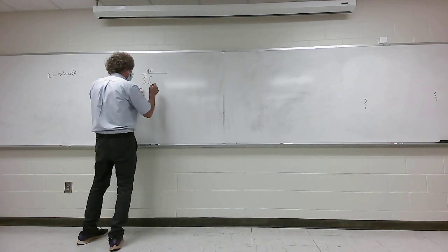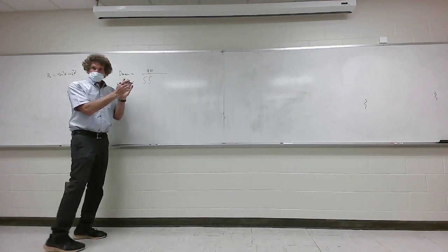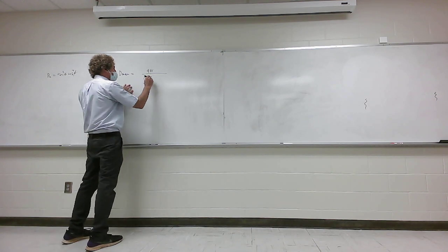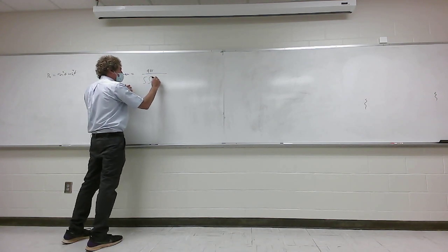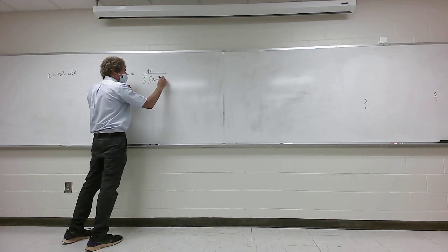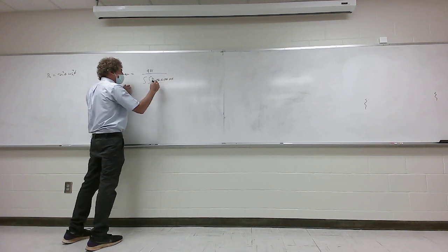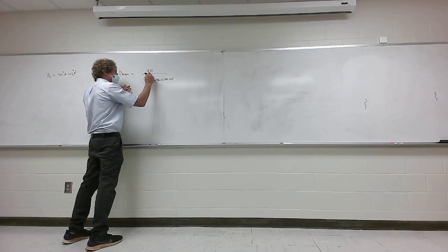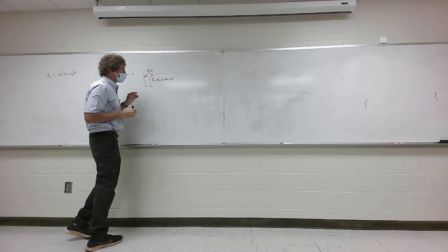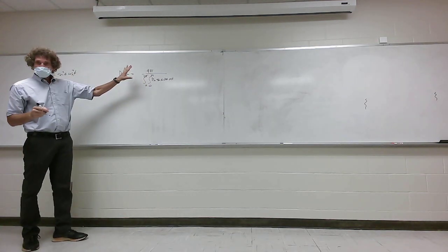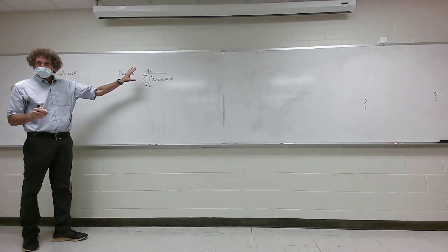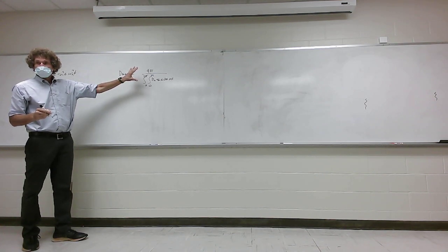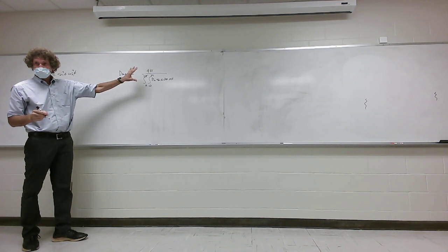This is the double integral of the normalized power density, right? Let me just put it up first. It's P normal, times sine of theta d theta d phi. Theta goes from 0 to pi, and phi goes from 0 to 2 pi, technically. That's the definition of D max, and you have to know this. You all with me?